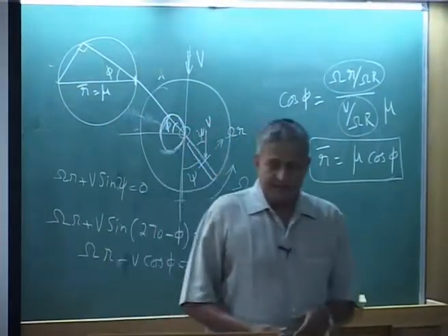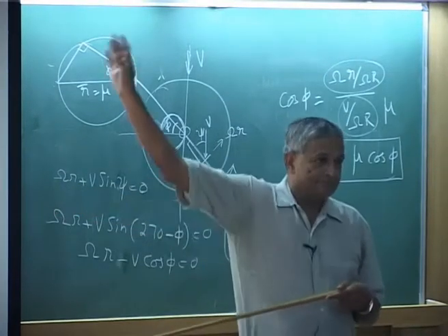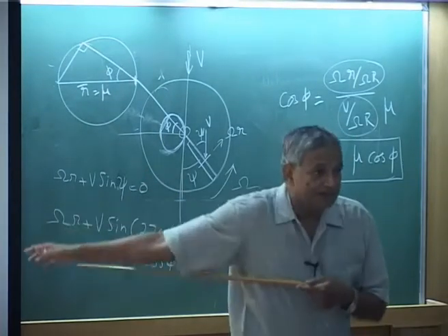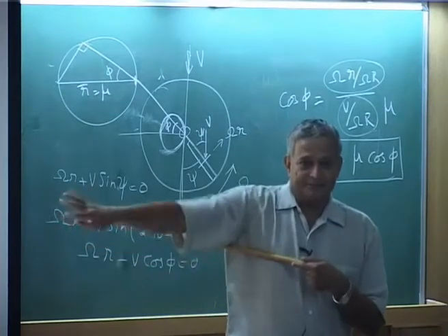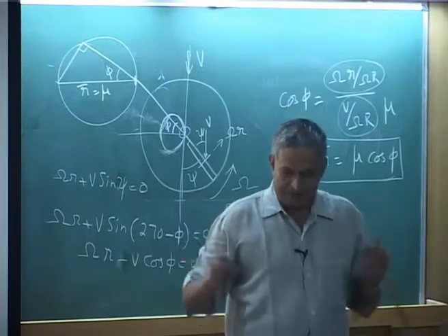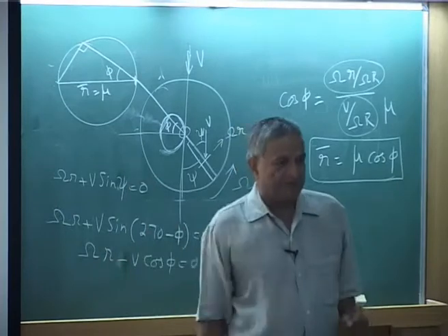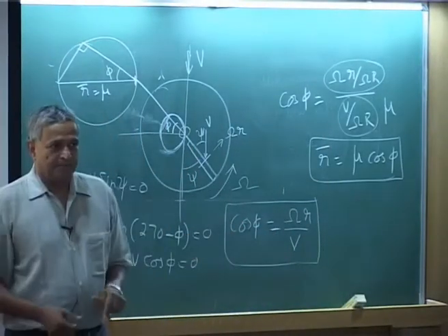Okay, blade is a beam. The beam can bend up and down, beam can bend this way also, and then it can have elastic twist, only these motions. Of course, centrifugal force is pulling, please understand, that is always there. So, you have these motions, which are blade motions.